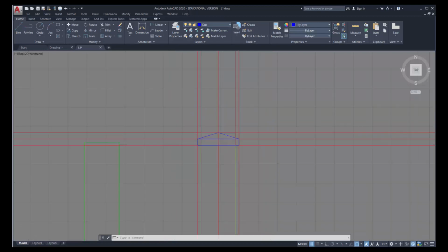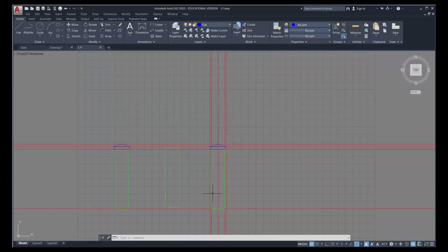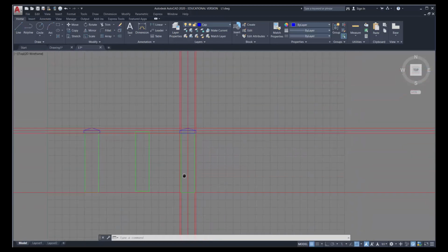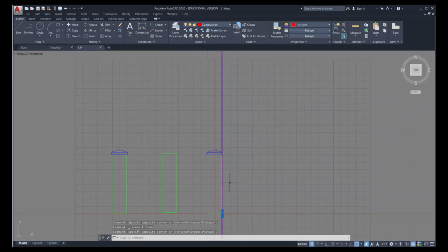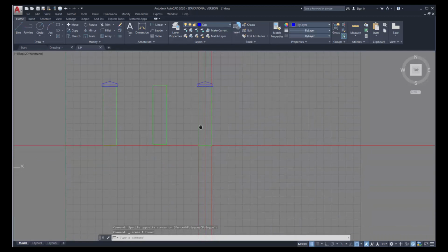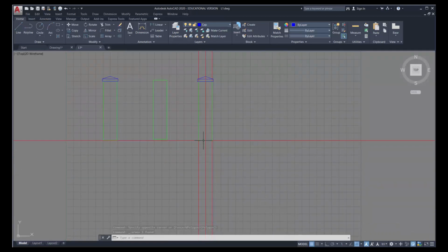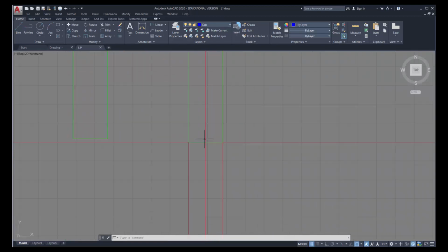So let's move down towards the bottom part of this, the foundation. With construction lines, it can get very busy, as you can see here. So once we've used these construction lines, let's delete them. We don't need them anymore. I need the center one. I need the edges of the column, but I don't need these two here. There we go. I'm going to keep the base. We're going to work on the bottom of this, which is the foundation and then the footing.